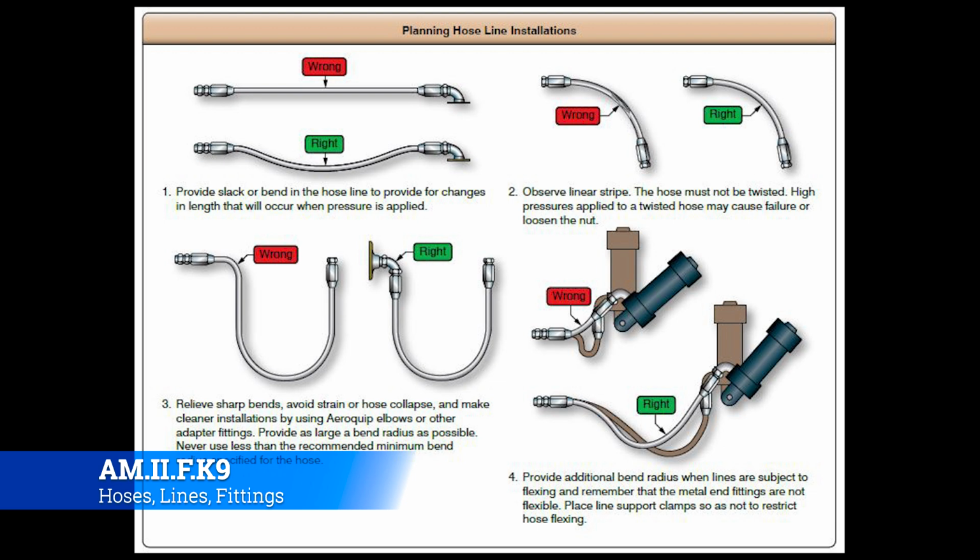Now, here's another thing to keep in mind. A lot of these, especially hydraulic lines, are braided. All right. Now they're not always braided on the outside. You can have braided cotton sleeves that go over the rubber hose that's on the inside, but most of the time with hydraulics, especially heavy commercial hydraulics, you're going to end up having steel braided lines on the outside. Now, whenever you see one of those plates, the rule of thumb is that no more than two wires from one of those little braid plates can be loose, or else the hose needs to come off and get replaced.